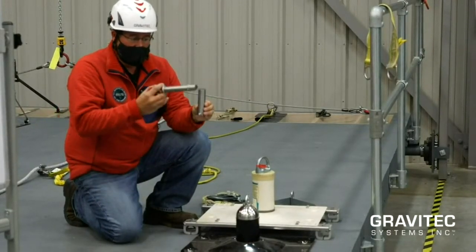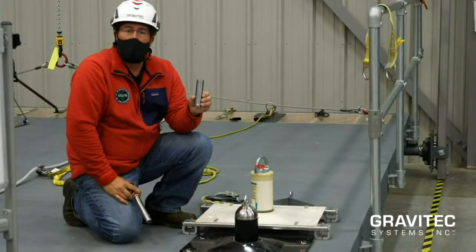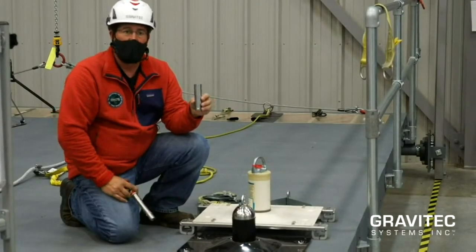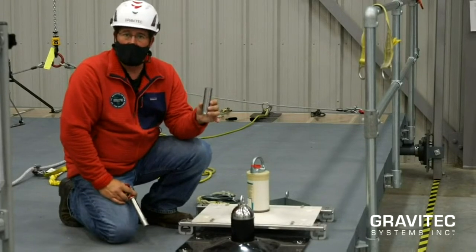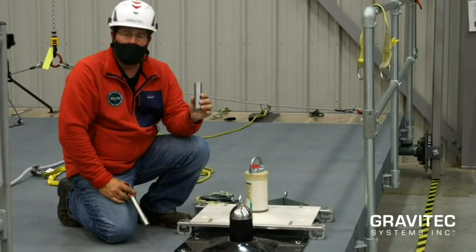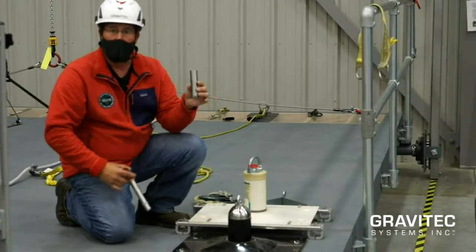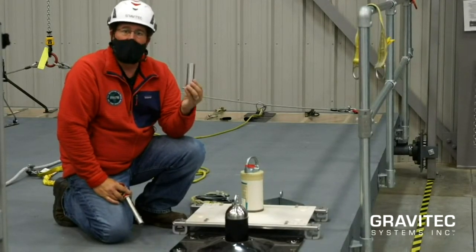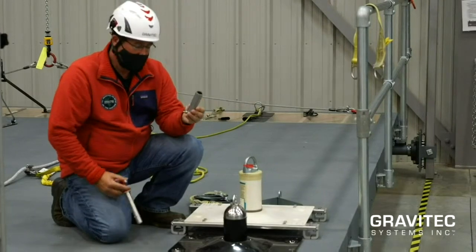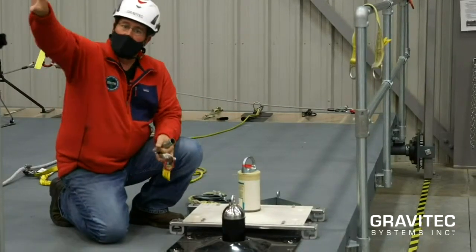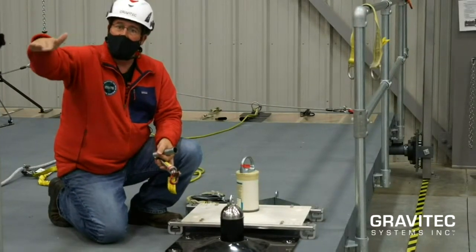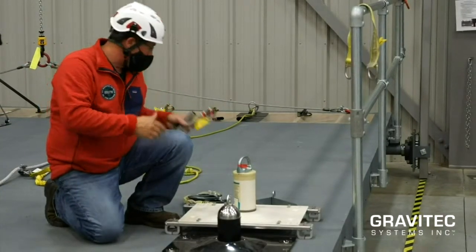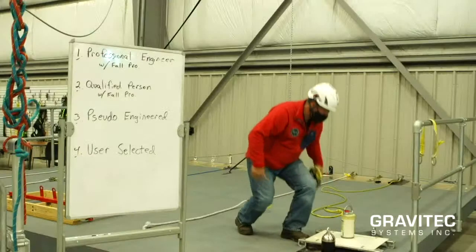As long as I get the minimum embedment into the concrete according to what the manufacturer specified, and there'll also be a spec for, you know, 2,500 or 3,000 PSI concrete. I'm making the numbers up as I go along. But the idea is that there's an installation spec to get the required strength out of this anchor. So again, it falls short of certification, but you get quite a bit of confidence when you use and install these correctly.